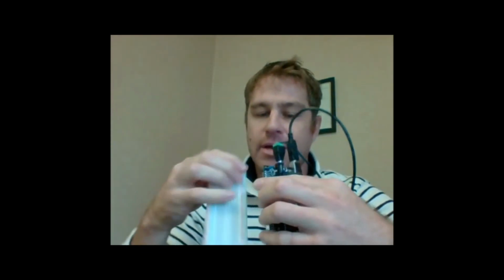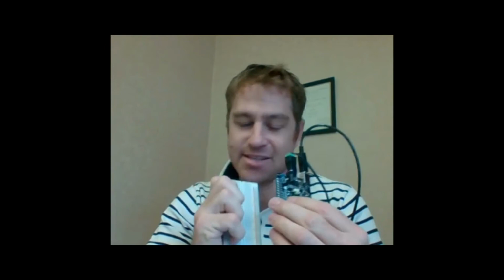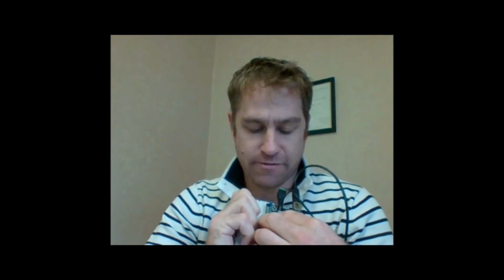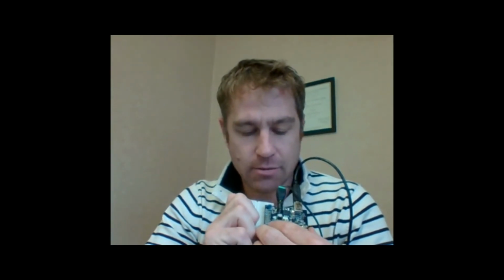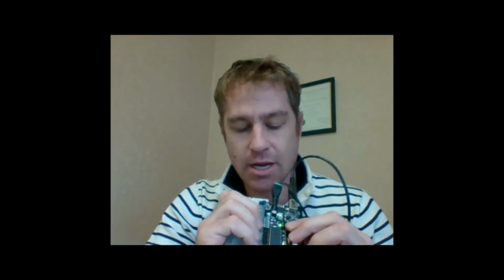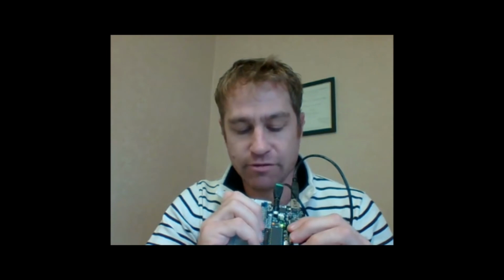Okay, so we're going to do this again. I'm going to flip it around. That's a good example of doing the thing the wrong way. So we're going to do it the right way this time. We're going to put our V plus in the red rail, the ground in the blue rail, and our header is going to be in the first column of the horizontal traces, right? So then once I'm properly aligned, I just punch it all in.